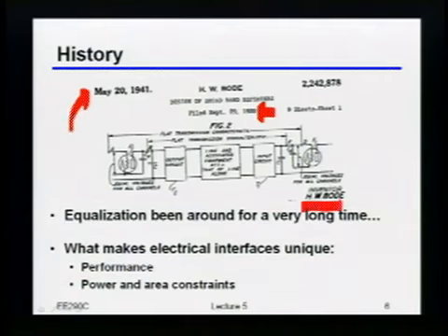Because basically you had these long cables people were stringing trying to get across the United States, and of course, cable has loss, just like we talked about. So even way back then, they said, well, I still want to hear everybody's voice. So they built these little equalization systems just to make sure that cable would effectively allow you to transfer over these very long distances. So again, equalization as a topic in general is definitely not new. Definitely not something that's been invented just for high-speed links.